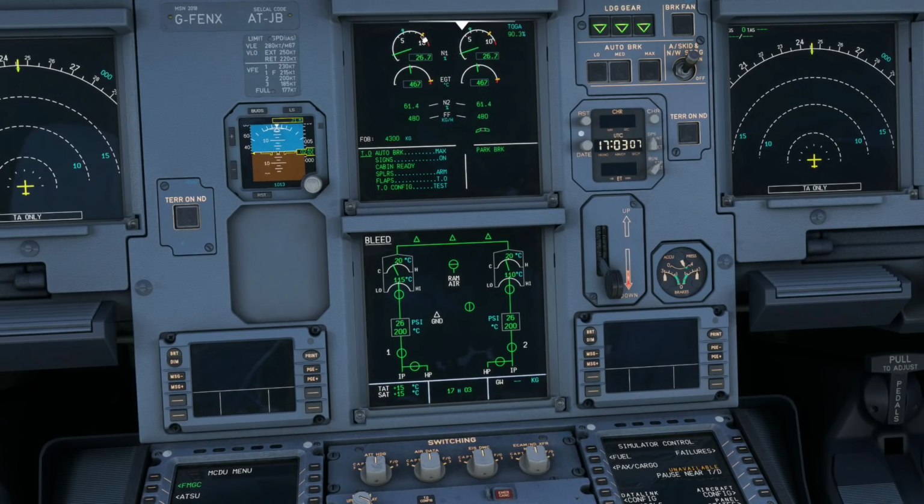So put some power in. There we go. So there's a bunch of N1, and you'll see it immediately goes amber, and it has basically said, okay, we've got more than enough from the intermediate pressure stage. We don't need any of the high pressure stuff. So we're going to close that valve off, and we're going to leave it be for the minute.